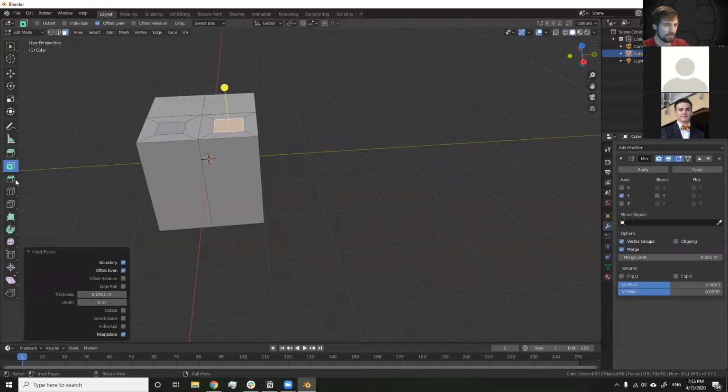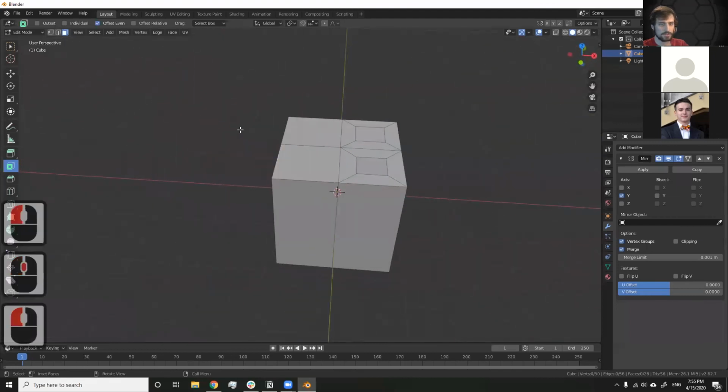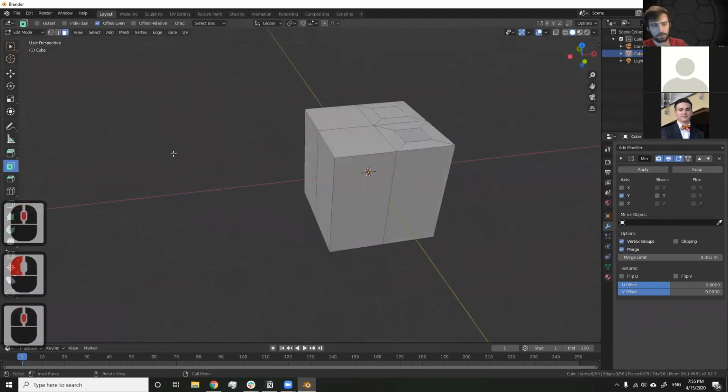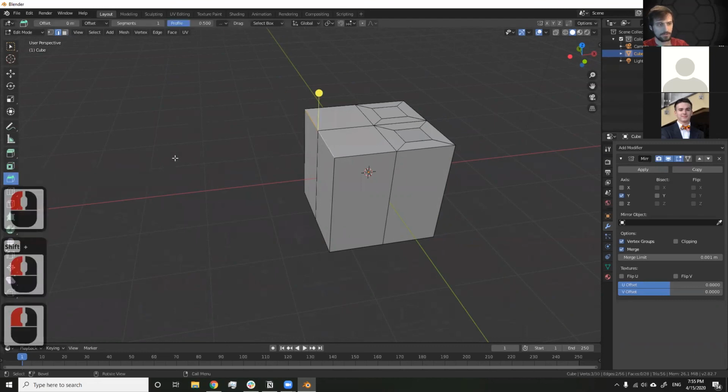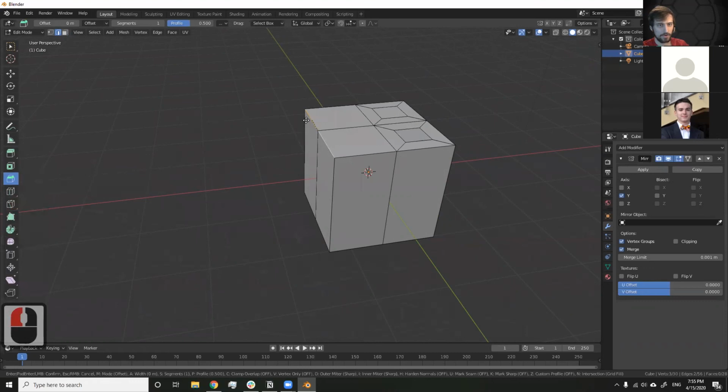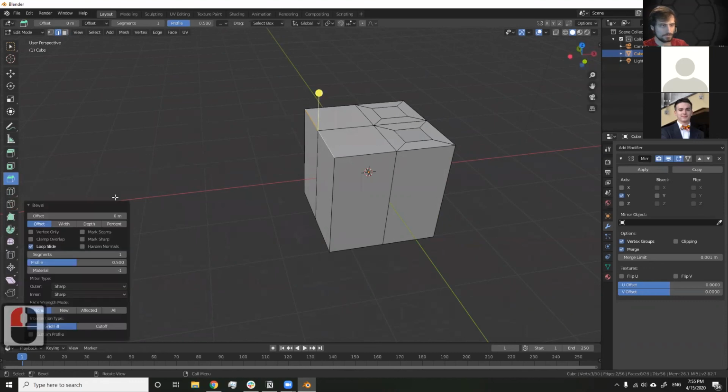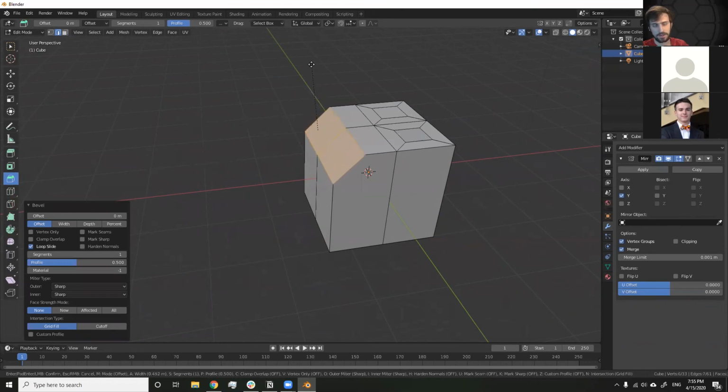You can also use this tool below it that's very helpful. This is the bevel tool. If you're familiar with chamfers and fillets in a CAD program, that's the equivalent in Blender here. So if I hit 2 to go into edge selection mode, I can select these two edges here, for example, and then I can go onto bevel, and now I can drag this out and I can create a chamfer in effect right across this edge here.